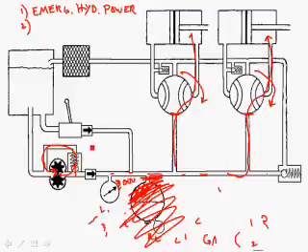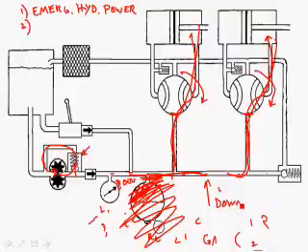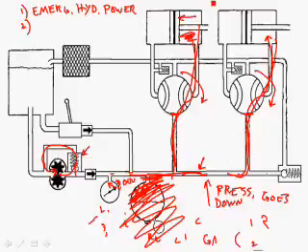Well, this valve over here, the pressure regulating valve, doesn't move instantaneously. If fluid in here gets to move somewhere else, then the pressure in here is going to go down. Just like in your house, if you turn on a bunch of water faucets simultaneously, the water pressure inside of your house pipes is going to go down a little bit. What's going to happen is the pressure is going to go down, and if we have less pressure in here, it won't exert as much force. Remember, force equals area times pressure. So if pressure is less and area is constant, force is going to be less.